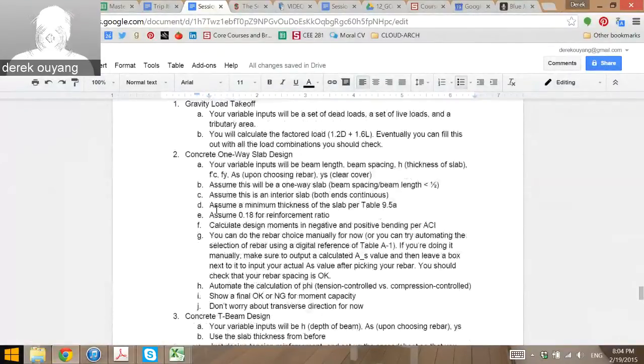The last thing I'll say is be very clear about how you're designing this. So you get your gravity load, your wu requirement just from the architecture, and it's either pretty standard or they're telling you that this is a tower with trees, right? So we've got like a green roof skyscraper. Every single balcony has trees on it. Obviously, that's changing your dead load, right? And you can almost consider that a live load, depending on winter or spring, whatever. But that would be the only condition in which you have significantly different gravity needs, right? If they decide to put elephants or trees or whatever.